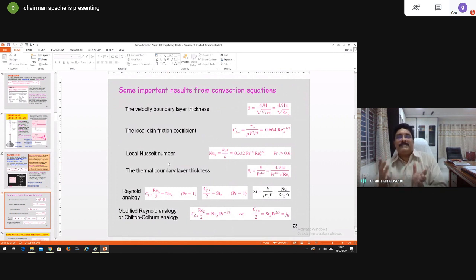Okay. And what is the parameter that influences? It is the Reynolds number. Now, Reynolds number straight away talks about the flow patterns. Based on the Reynolds number, you decide. When Reynolds number is less than a critical value, normally the flow is treated to be laminar, and when Reynolds number is greater than a critical value, we call it turbulent. What is Reynolds number? Inertia force divided by viscous force. This also we made very clear in the last class. What is inertia? What is viscous force? How these forces come into the picture, with an explanation I gave.